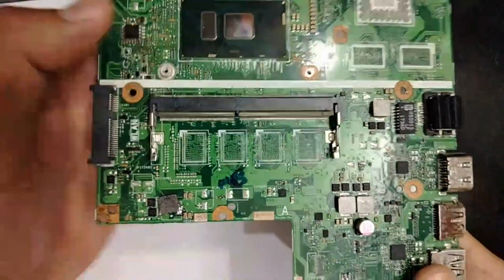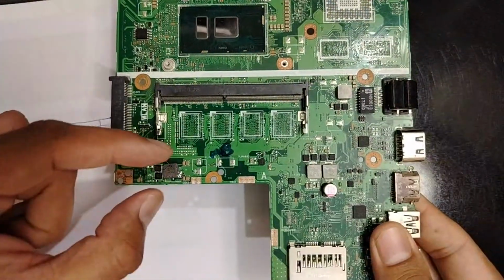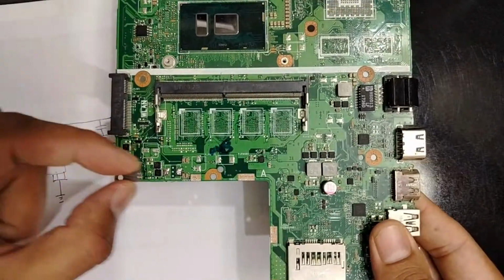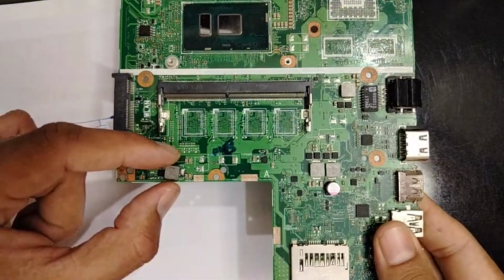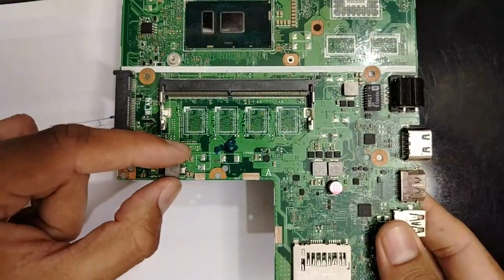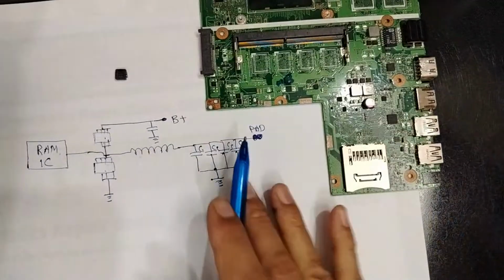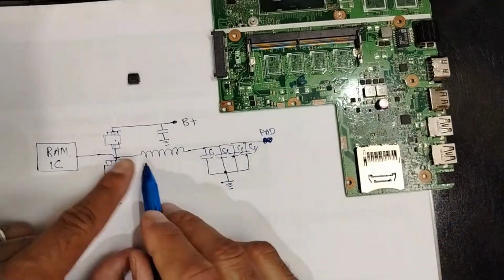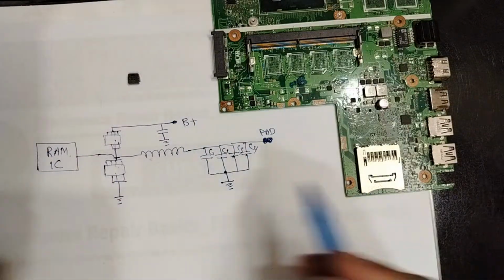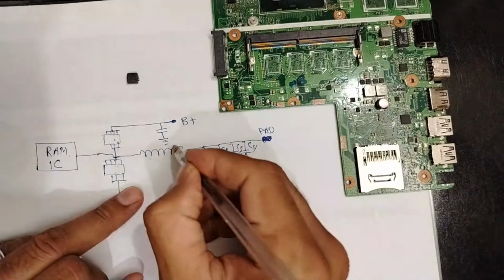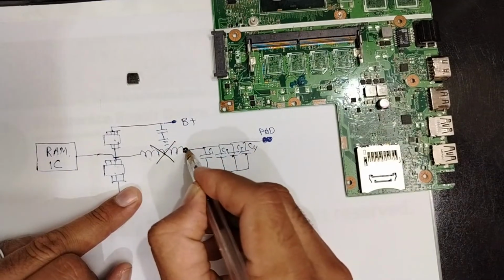But first, once I remove the inductor here, normally the short in the first time was on both sides. Before, the short is everywhere in the circuit, but once I remove this one, I get the short just at this point.